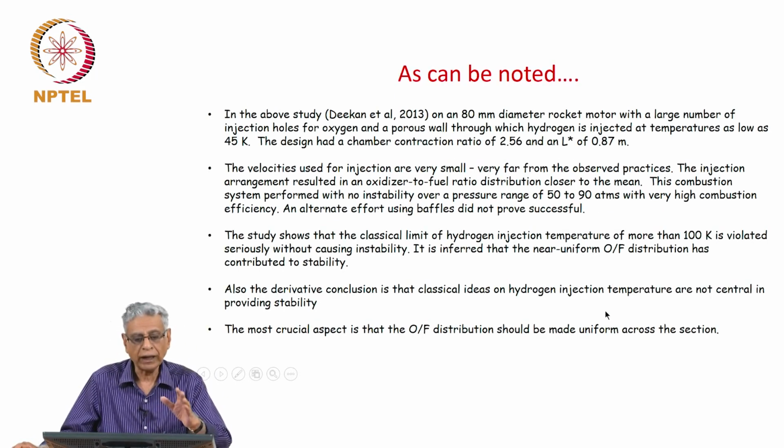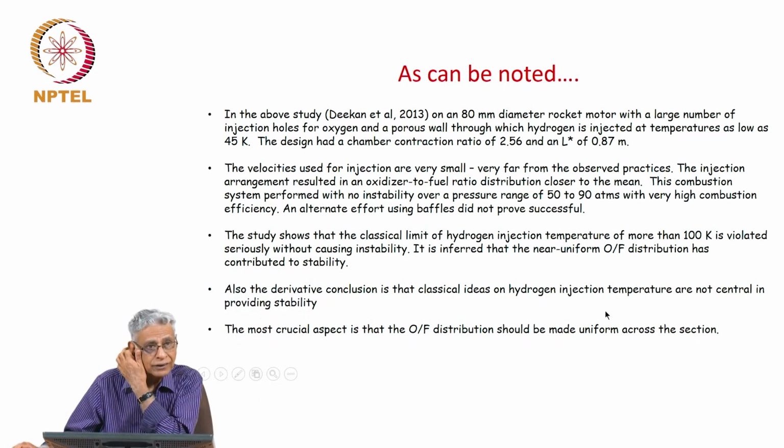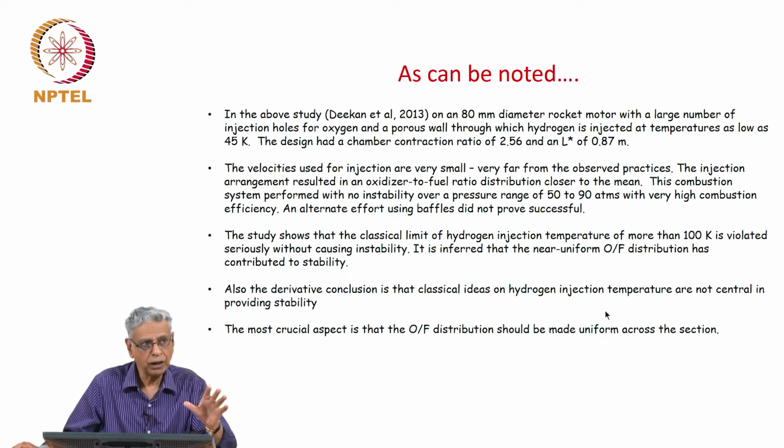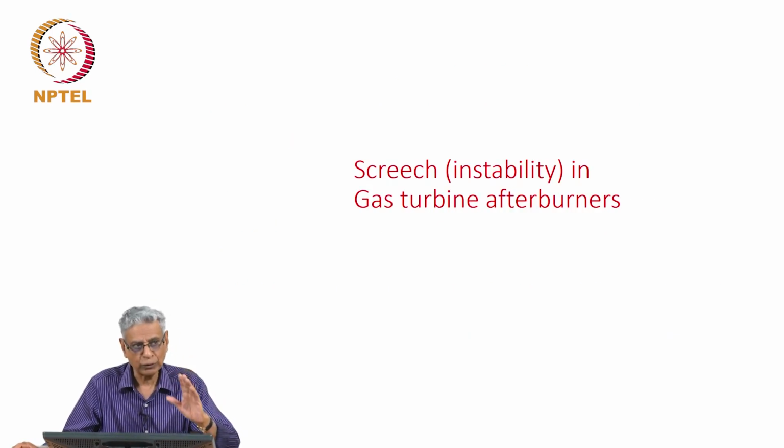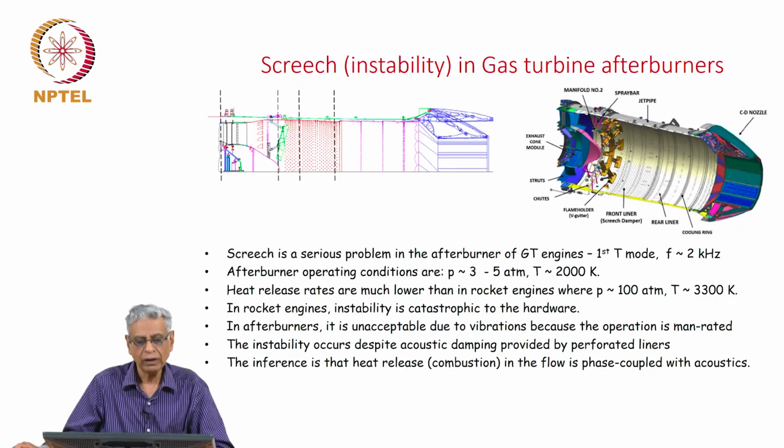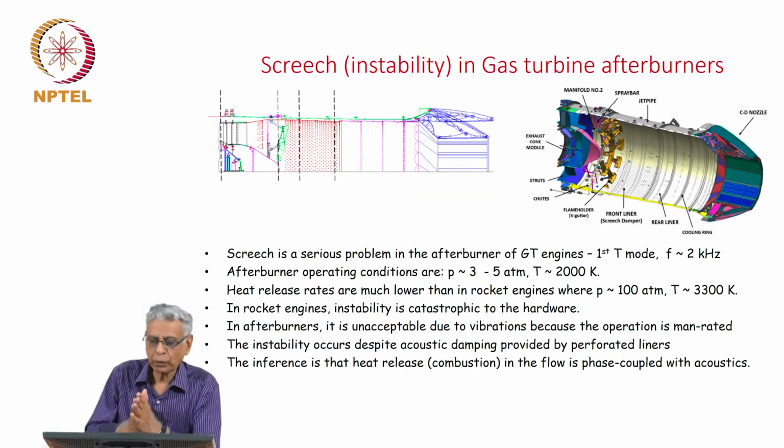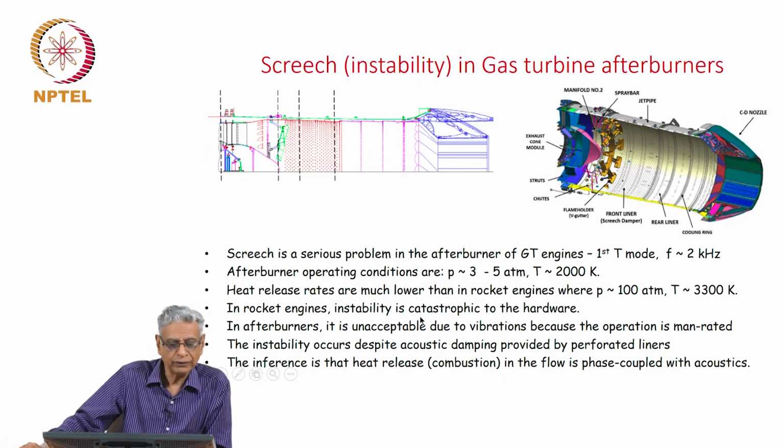I think I've said what I need to say about liquid rocket engines. The ideas are very similar, and you will discover this in the case of gas turbines as well, afterburners as well. Let me look at this. This is a gas turbine engine taken from GTRE's documentation. You have the flow coming from the turbine, and you will find a number of holes, a perforated sheet here. As I mentioned earlier, it becomes an acoustic absorber.